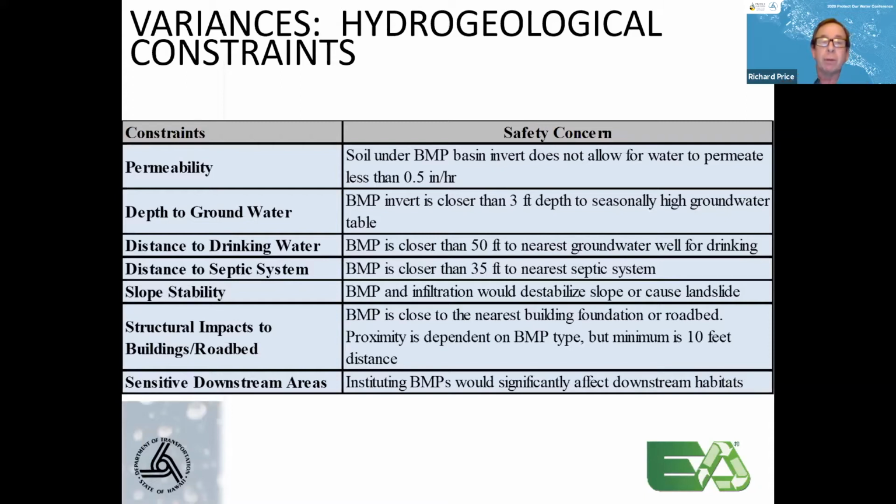And then another major concern is slope stability. Where I live in the city of Seattle, the city maintains a very detailed GIS map of all the steep slope areas, and there is a 50-foot setback at the top of those slopes, because if you were to infiltrate a large volume of water at the top of a slope, you can supersaturate the soils and cause instability in the slope. It will cause a slope failure. There was, several years ago, the Oso landslide, where the whole hill came down and blocked the river and destroyed an entire neighborhood in Washington. And there was some thought that that was caused by a logging project at the top of the hill that clear cut an area and increased the infiltration at the top of that hill and saturated the hill slope. So it's a significant and real risk that we want to avoid.